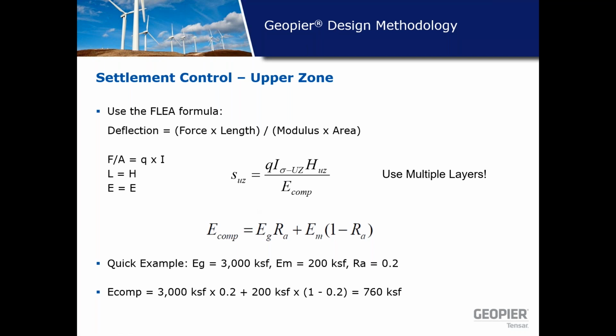And what I mean by that is if you were to look down from space at a plan view of an excavation for a foundation, and you could see the pier elements and you could see the soil in between, and you say, oh, about 10% of that area is composed of the pier elements and 90% is the soil. We just take a weighted average.